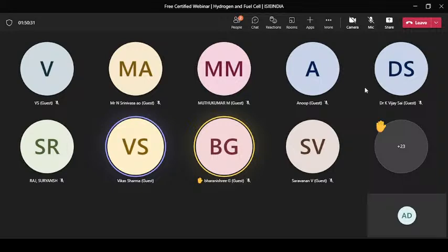And if we use, as in the example I gave of the Toyota Mirai, it uses the hydrogen in gaseous form, but due to its very low density, suppose there is a petrol tank of 30 liters, and we know that the hydrogen gas density is very low, in that 30-liter tank only about half a kg of hydrogen will be stored.